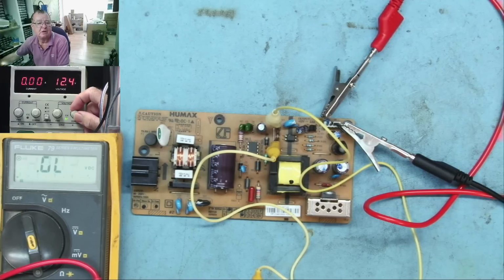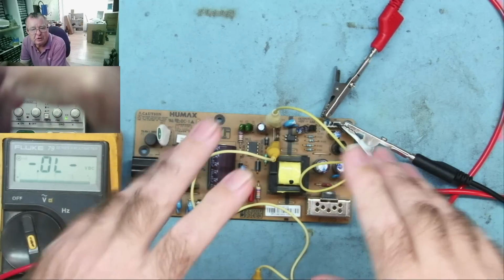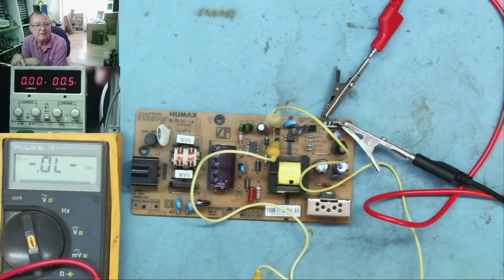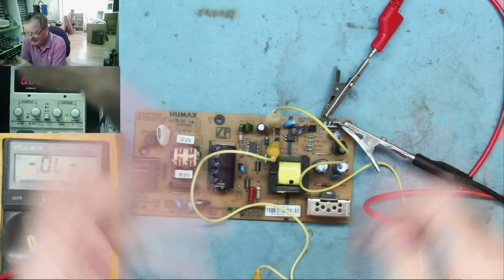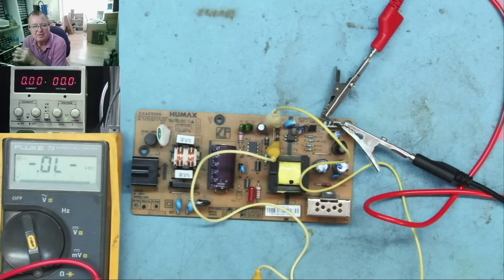Well, we're at 12 volts now. Let's go a bit higher. And there, got it. Okay. So just at the point we go above 12, I'll alter the fine voltage adjustment. 12.1, 12.2, there. Okay, come back down again, it's off. So you can see very clearly, I can test the whole feedback circuit of this power supply. There, okay. So if you ever suspect there's a problem with the feedback circuit on the switch mode that you're repairing, that is an extremely simple way to test that.